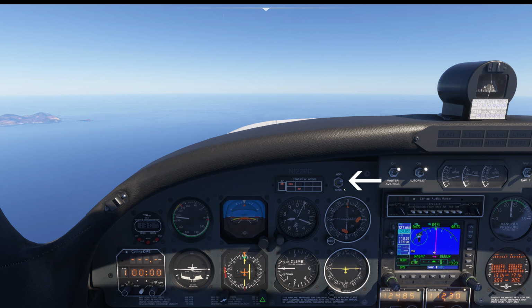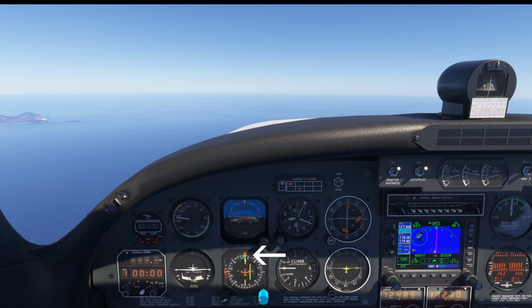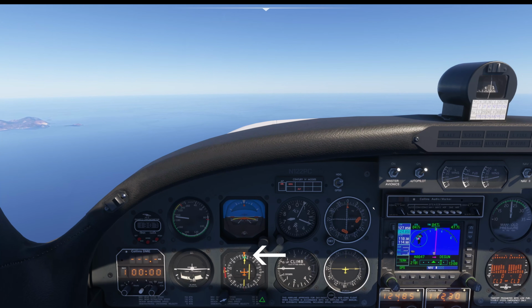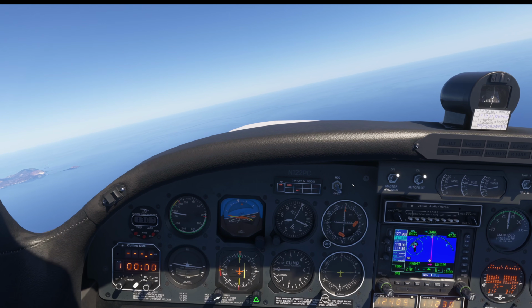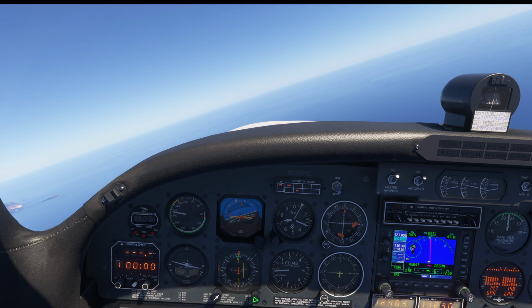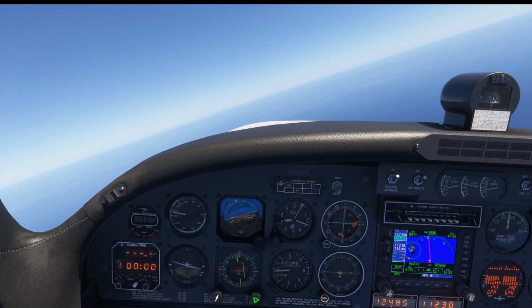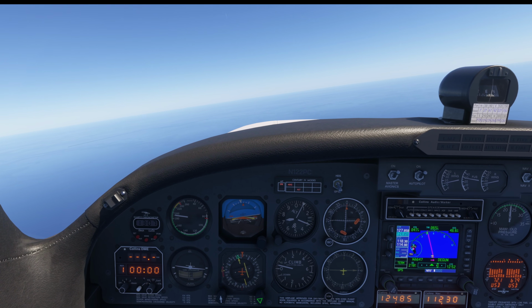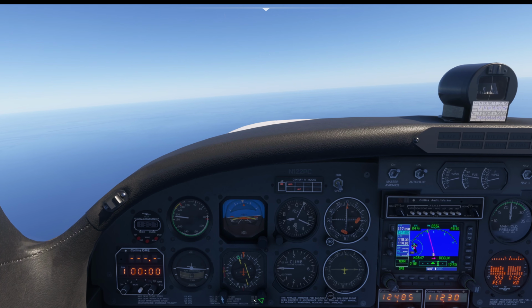This switch in the cockpit is used to control what is being sent to the autopilot. If the switch is in heading position, the autopilot will follow heading bug, just like it would without GPS module installed. If the switch is in GPSS position, then GPSS module is in control, and it steers the autopilot according to GPS commands. In this mode, the heading bug is disconnected from the system. Moving it has no effect.